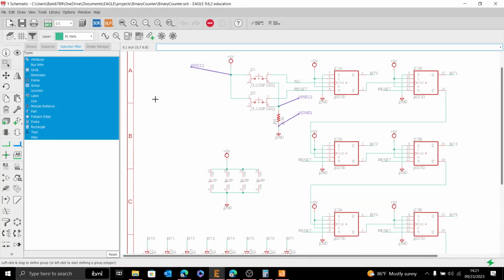I extracted the single component I needed, got it in. Oh, the nets don't match up. Okay, well, let's make the nets match. Hey, the nets match. What are you going to use for a button? I give up. So, hypothetically, there is a way. My personal recommendation, download LT Spice and do it externally, so that way everything just works nicely. There are some components that are a little too challenging to simulate, like a microcontroller, and the idea there is you extract the logic you want to test,